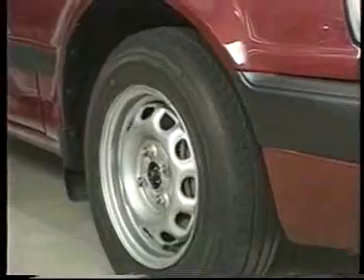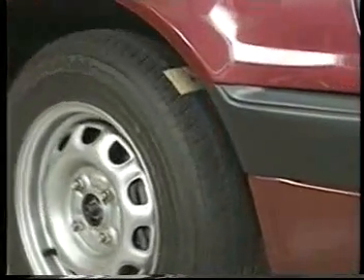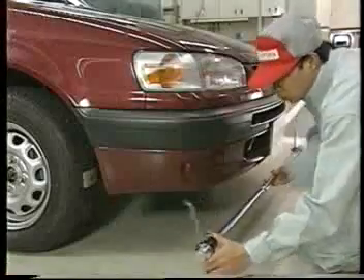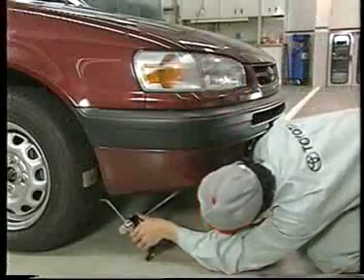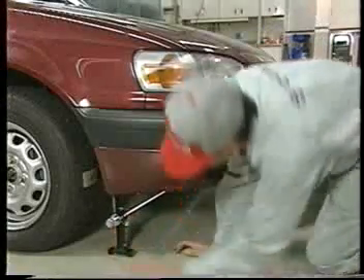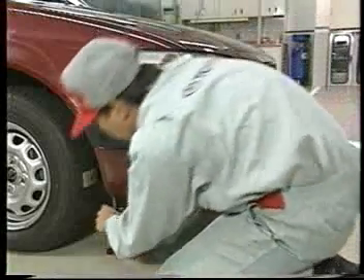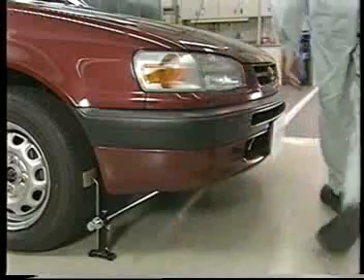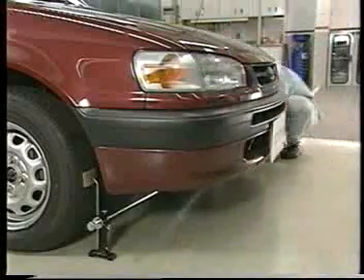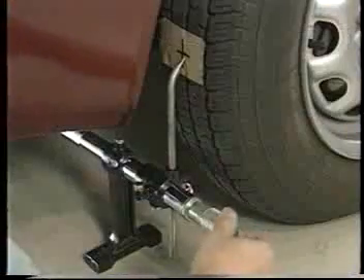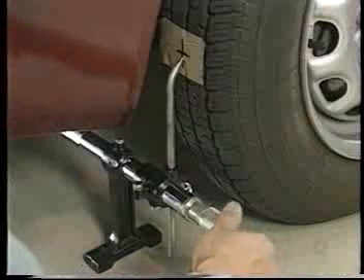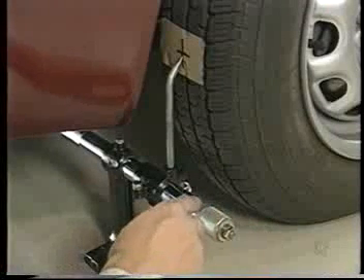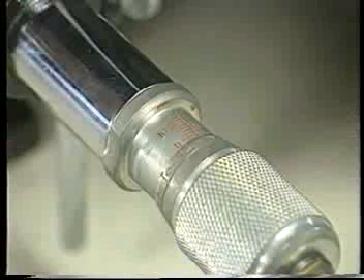Then move the vehicle forward until the marks on the rear of the tires come to the height of the gauge placed in front of the tires. If the tires roll too far, do not move the vehicle back. Move the vehicle forward another 5 meters and start again. Measure the distance between the marks in the front of the tires. Then calculate the difference between this figure and the distance measured on the rear of the tires.